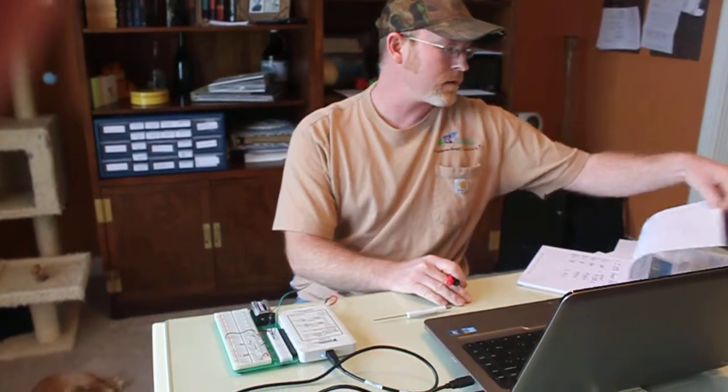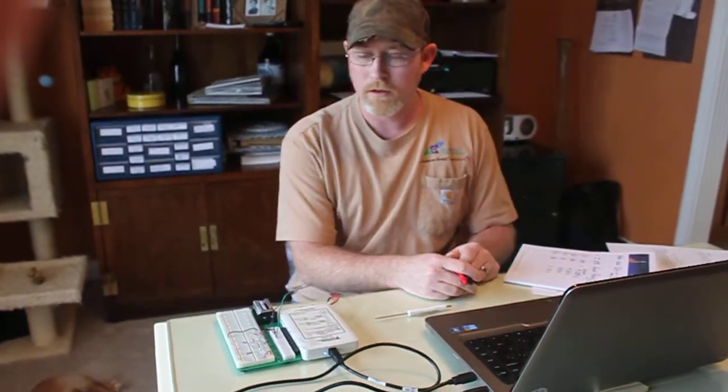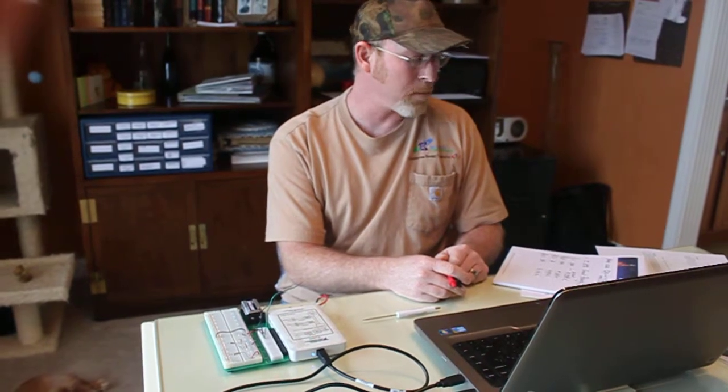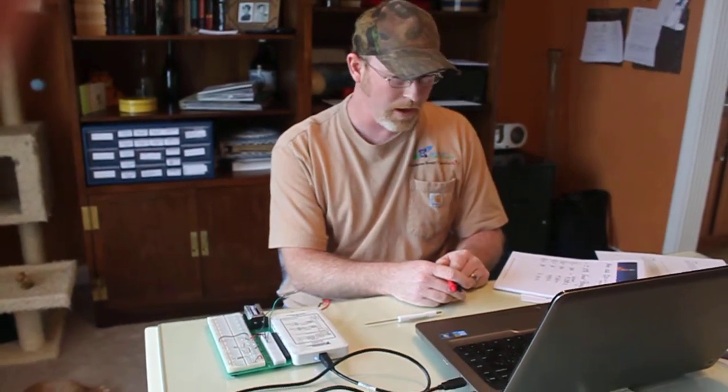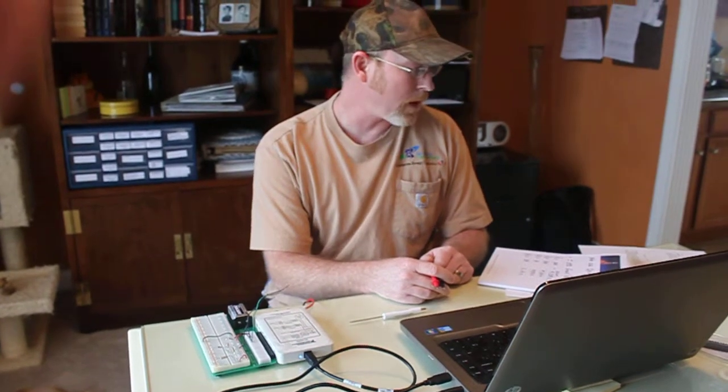Step 10 that I've got written down here, we're going to collect all that data and take a look at it, and we're going to see what's the best value for the load resistor for the maximum power transfer. And we want to keep in mind our error equation, which is what you got through your experiment minus what you got through your theory, divided by what you got through your theory, times 100. And if you fall within plus or minus 10% of that range, I would say you're safe to say that you've conducted the experiment fairly well.